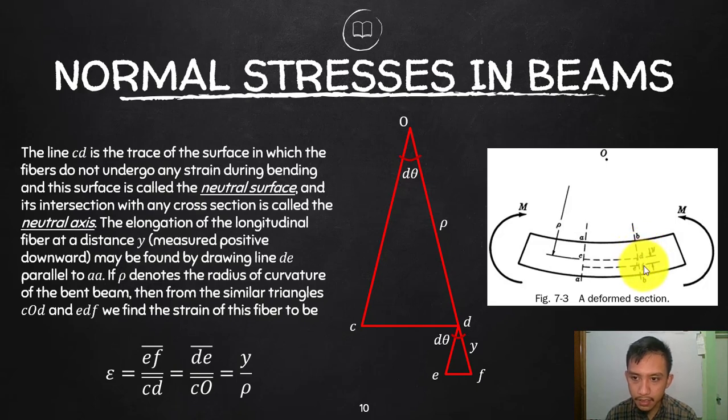And then this here is the additional length. Originally, the length is up to E, somewhere there. But because of tension, or elongation, or the strain, there will be an additional elongation of length EF. If you try to project that and approximate it also as a simple triangle, not a curved surface, then if that is a very, very small angle, we can now refer to these as similar triangles.